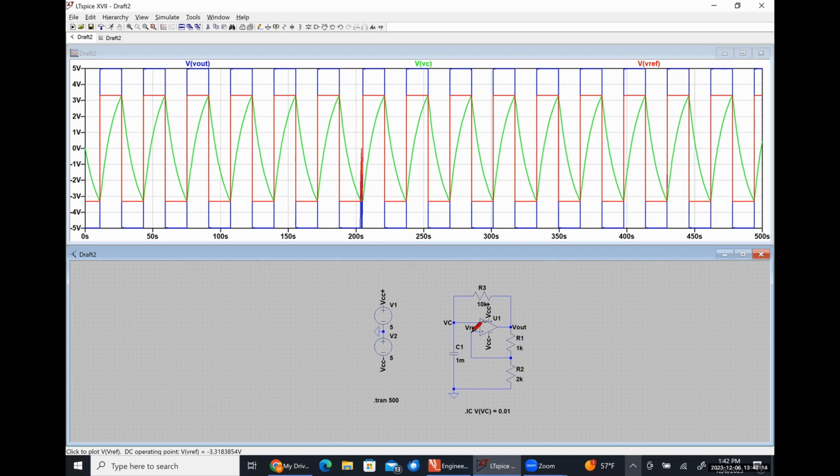So there's definitely your differential stage. Then there's a gain stage, then there's an output stage, and then you also have the stage that's for correction, offset, current biases, all that kind of stuff. We'll cover most of that later.